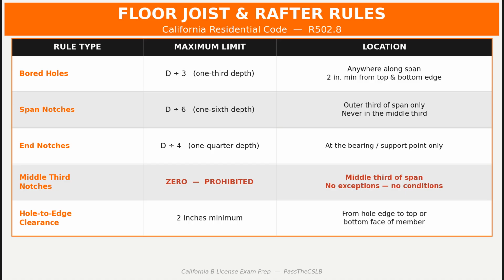Bored holes are governed by a third principle. When you drill through the approximate center of a joist's depth, you are removing material near the neutral axis, the imaginary horizontal line through the middle of the section where compression becomes tension and net stress is 0.